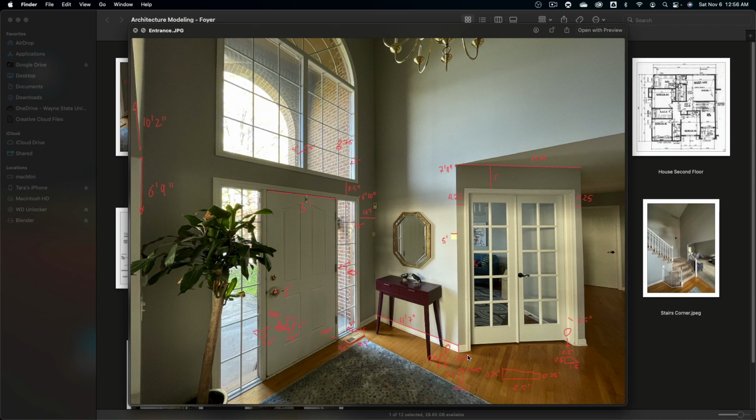The hardwood floor isn't really cut to touch the baseboard. There needs to be a little bit of a gap because during the summer or winter, when air moisture changes, the wood expands and shrinks. So the gap will get bigger and smaller. Not much, but enough. So we have then this quarter round that goes around it.